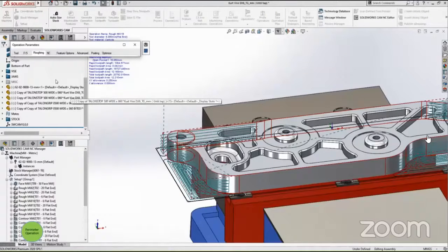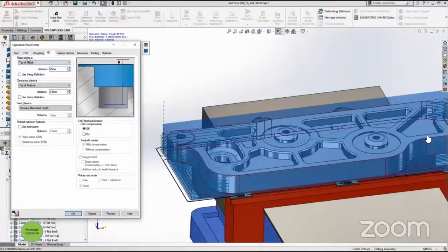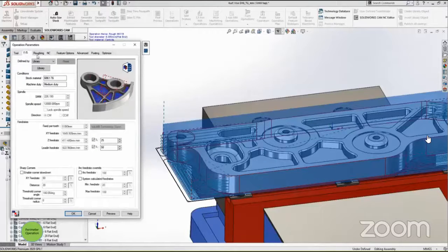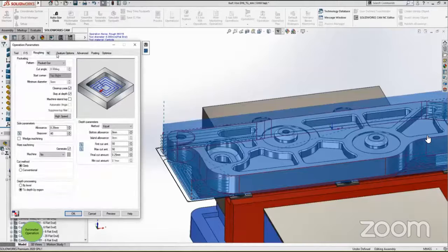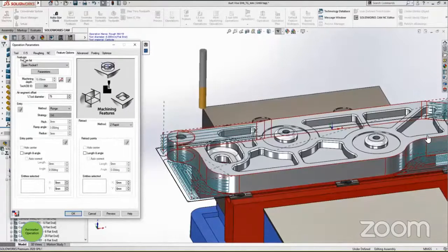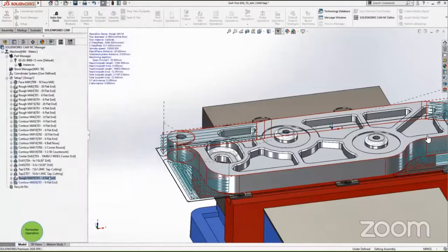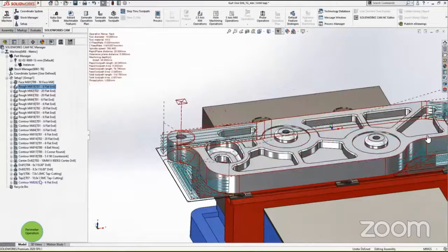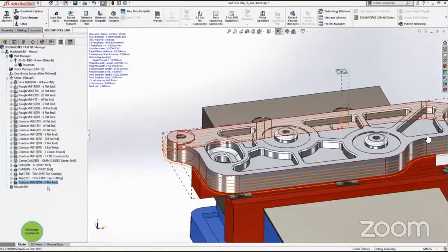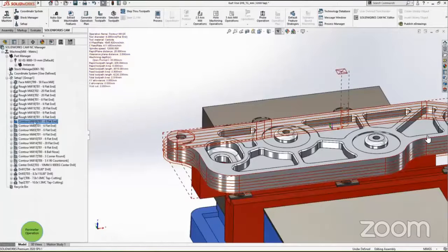Here we can see those tool paths which were on the top face are now gone, and we have the tool paths only at the sides of the CAD file. We'll specify the setup definition as well on this operation so that the tool will not collide with the material of the stock. We don't have to specify any machining depth, and then click OK. For roughing it is perfect, and for contouring, we don't have to specify the top island, since the contouring operation only performs machining on the sideways.